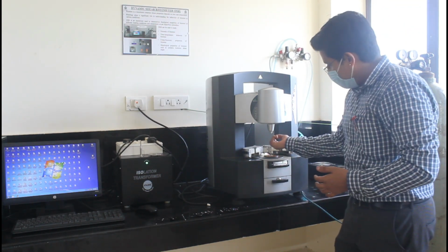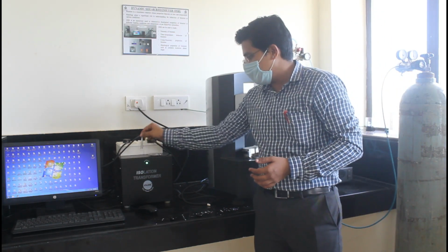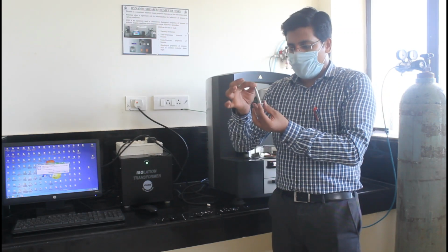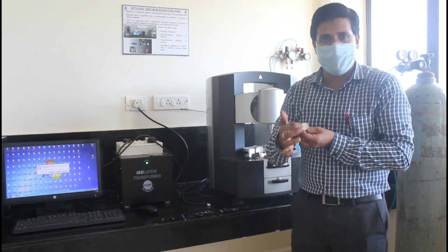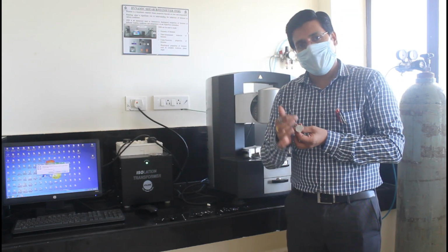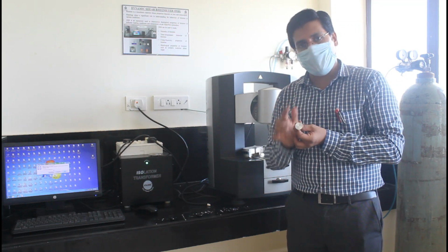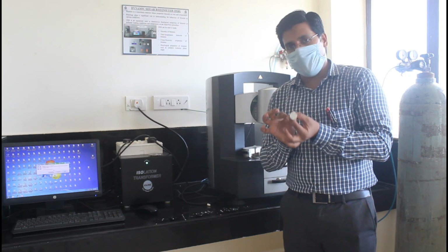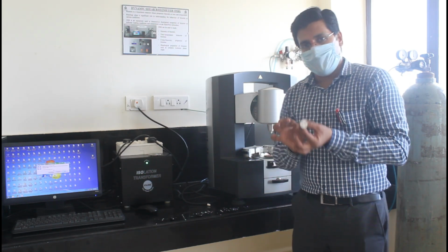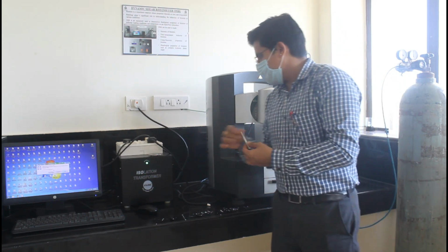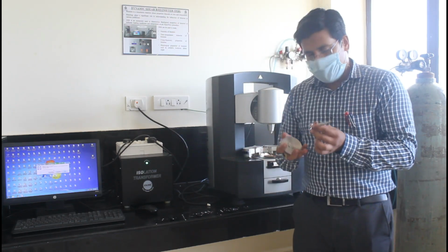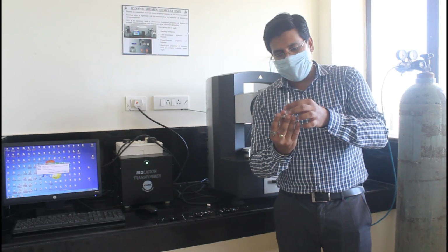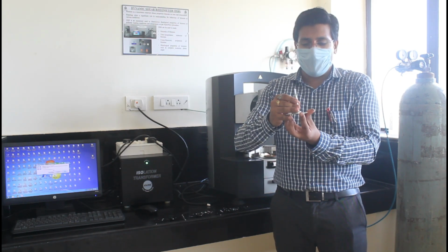Now at this particular point, we will fix a spindle. This particular plate is 25 mm in diameter. It is basically used to study bitumen which is RTFO aged and unaged. So in this case we go for the 25 mm diameter plate. Both things together form the parallel plate system. This plate is fixed and this plate, which is attached to the motor, will rotate, right?